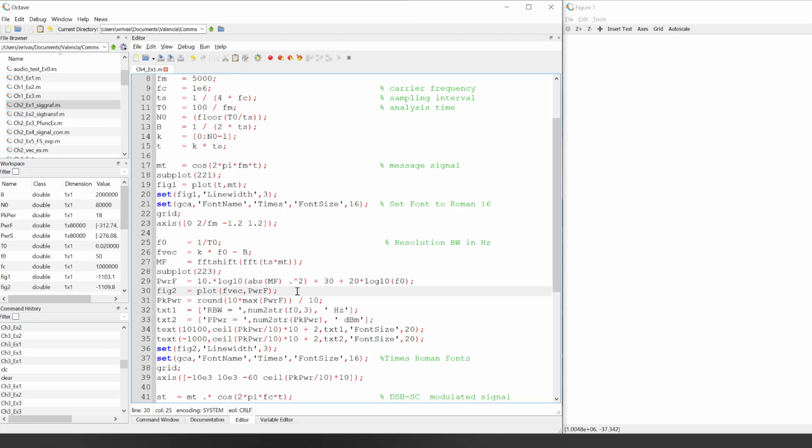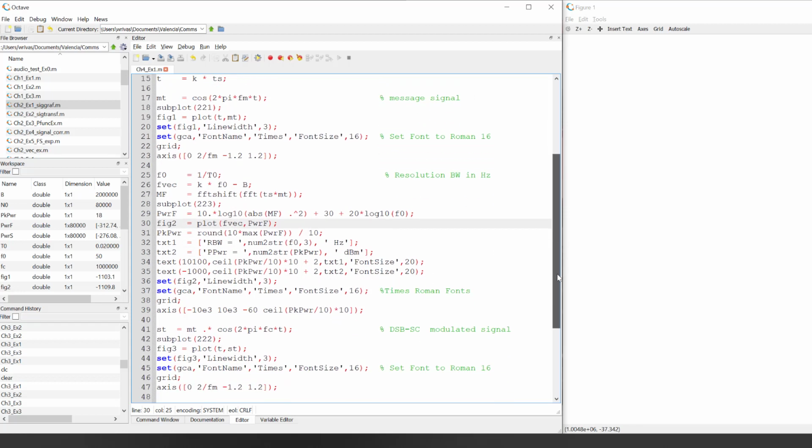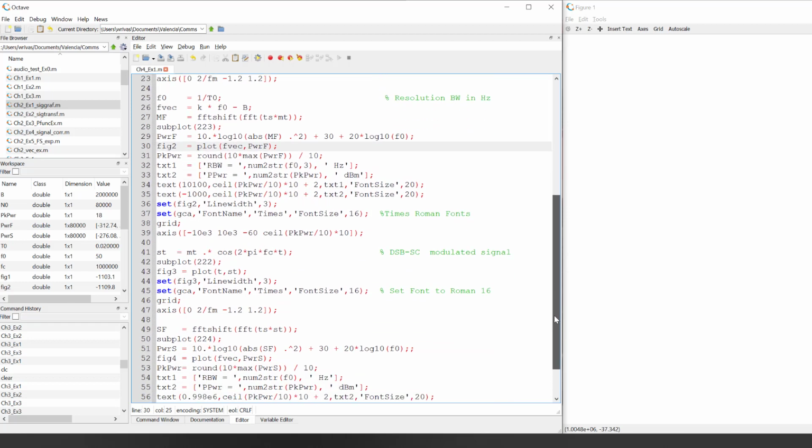Now, that's in voltage, and we're going to look at that in dB. So if you remember the dB, you would do 20 log of 1/2, which is minus 6 dB. And we should see that when we run this. You guys can kind of see what I'm leading up to. And in fact, that's what we get.